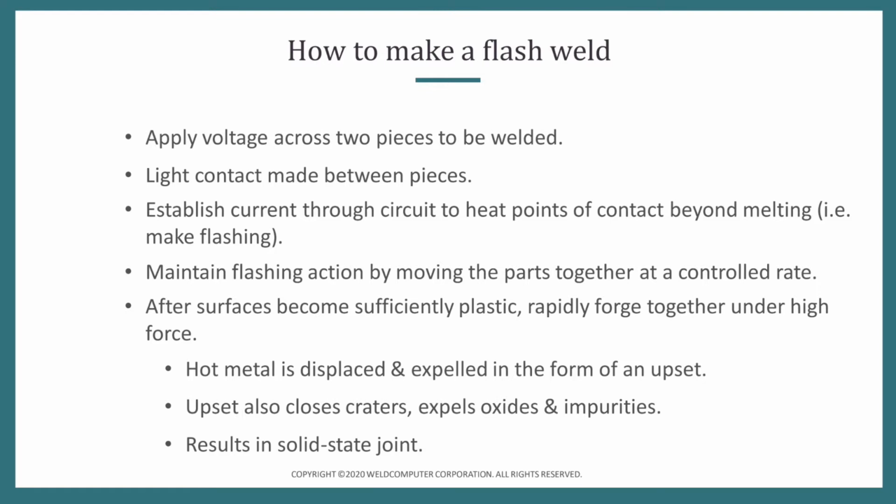There wasn't a lot of talk about how to actually maintain the flashing and control what would constitute a consistent amount of flashing, because everybody dials up a flashing time and distance. But at least I haven't seen much attention paid to looking into the energy that goes into the flashing during that flashing distance, because the consistency of that is an important factor so that you have a consistent end result when you are ready to go into upset. So a lot of what I'm going to talk about is really focusing around making that happen.